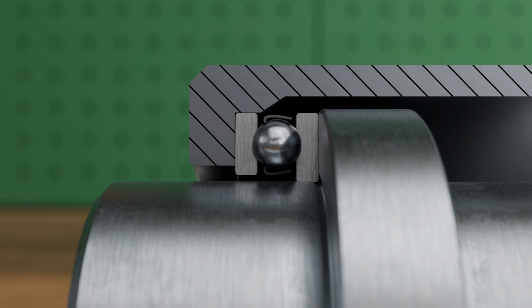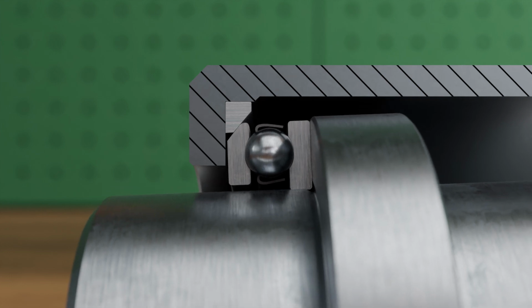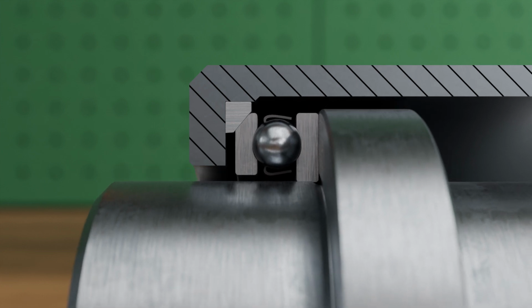deflections must be compensated. Therefore, there are thrust ball bearings with spherical housing washer, combined with a matching spherical seat washer. This special design allows the housing washer to align within the bearing housing, and enables compensation of misalignments up to 3 degrees. The thrust ball bearings presented so far can absorb axial forces only in one direction each.